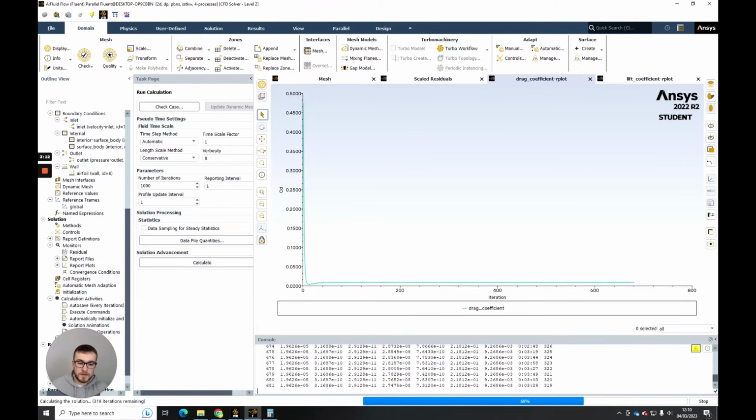You probably could get more accurate values than the ones I've got here, but again, that would take doing a mesh independent study, doing a domain size study, maybe looking at some more of the wall effects, improving the mesh quality, and taking a look at time dependent effects. There's lots of different things we could do to improve our accuracy, but improving accuracy takes improved effort and improved computational costs, so there are trade-offs to trying to get your answers as close as you can to experimental data.